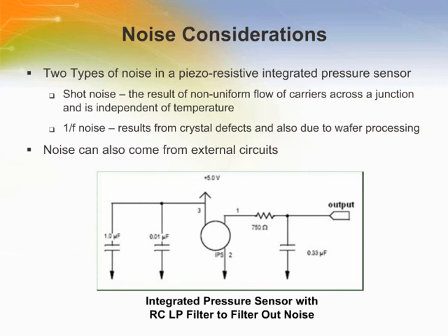For mitigating the effects of this sensor noise, two general approaches are effective: low-pass filtering with hardware and low-pass filtering with software. When filtering with hardware, a low-pass RC filter with a cutoff frequency of approximately 650 Hz is recommended.